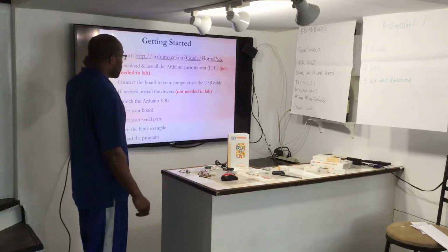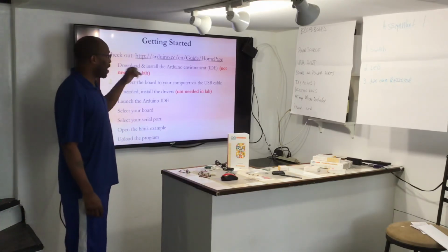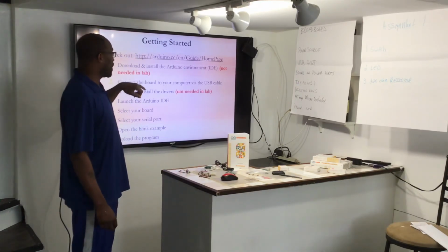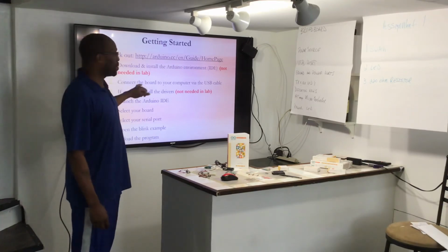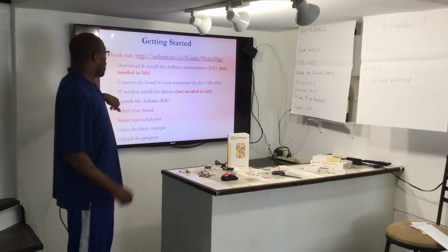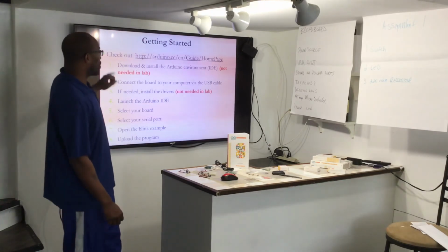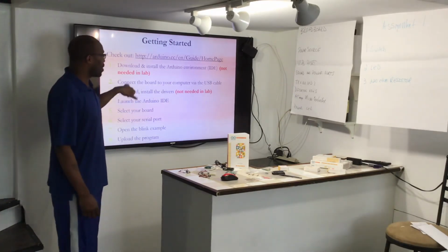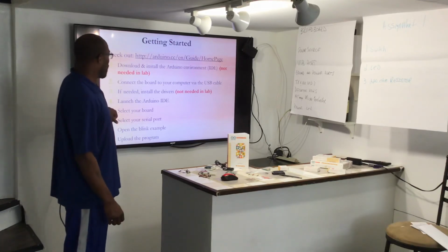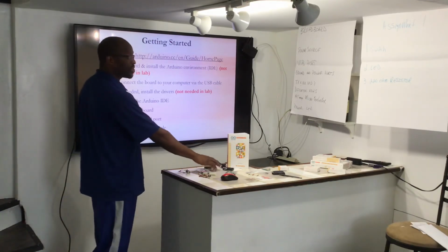At this page, we'll be able to download and install the Arduino environment, which is called the IDE. We'll connect our board to the computer by the USB cable. If we need to install drivers, that will be done at this site as well. We're going to launch the Arduino IDE program and select which board we're using, because there are different boards that you can use.